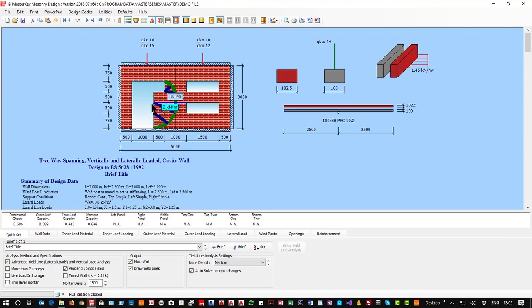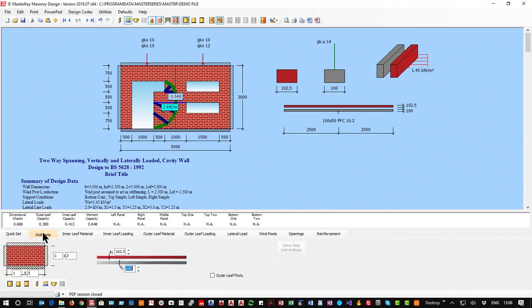And some people say to me, why horizontal line loads? Well, sometimes if you've got a racking system, you're going to have loads attached to the wall to stabilize your rack, or even barriers for crowds and things like that can produce a line load onto the wall at 1.5 meters high and things like that. So this is where we're going to get to eventually, but let us just start by taking a brand new wall,